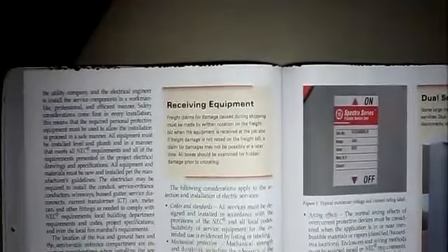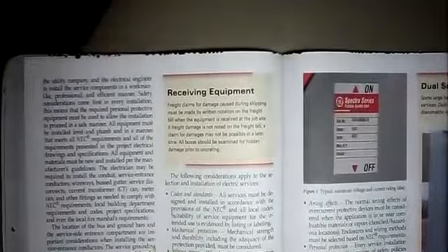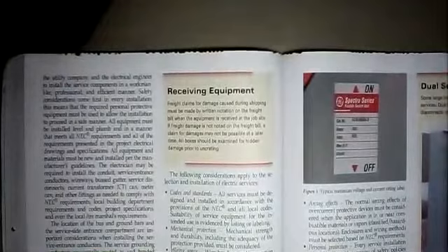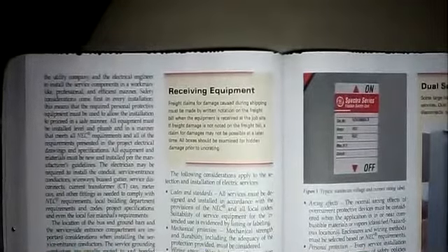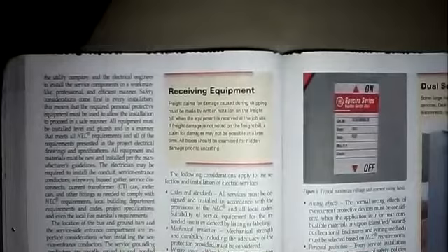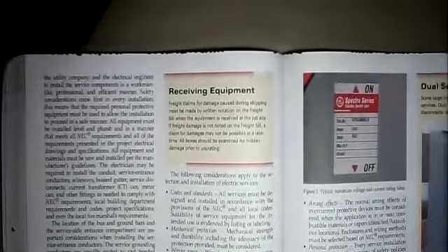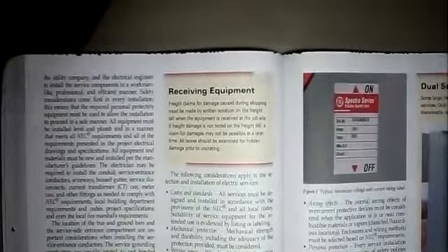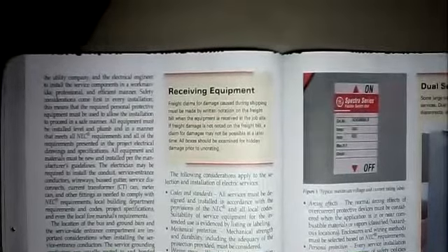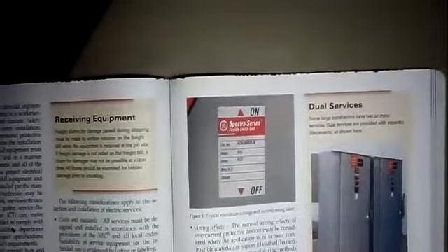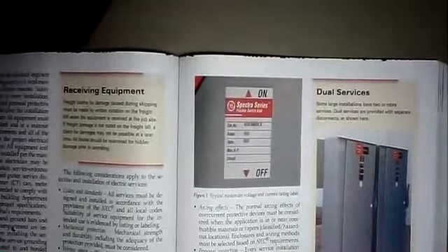Receiving equipment, I don't have any highlights, but they're going to tell you that you need to inspect any equipment that arrives on the job. You don't need to inspect internal wiring. If an apparatus is delivered to the job and the crate it came in looks in good shape and the outside of the device itself looks in good shape, you don't have to inspect the internal wiring of that piece of equipment. We can take it on faith that the internal wiring is still intact